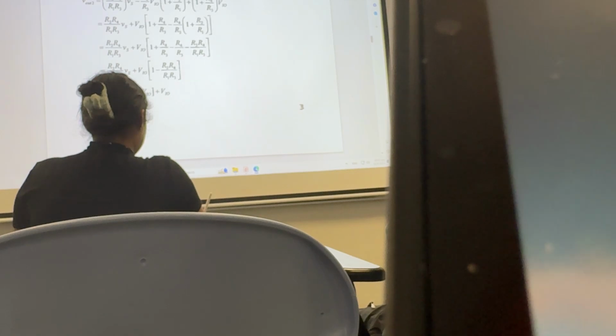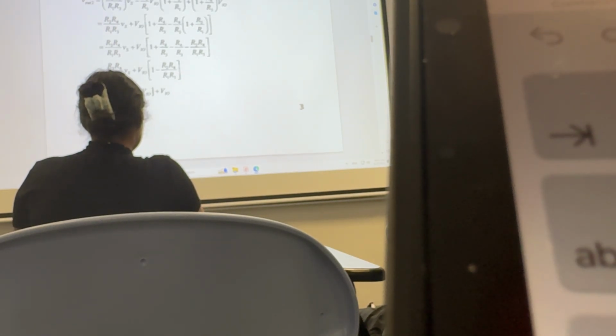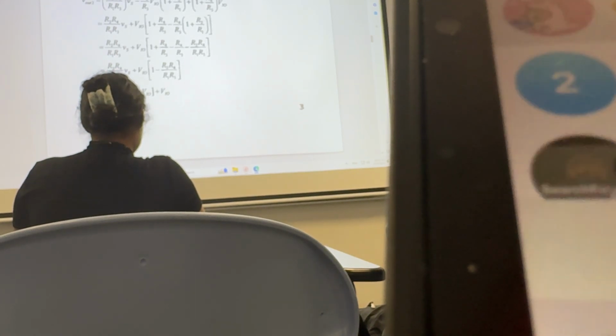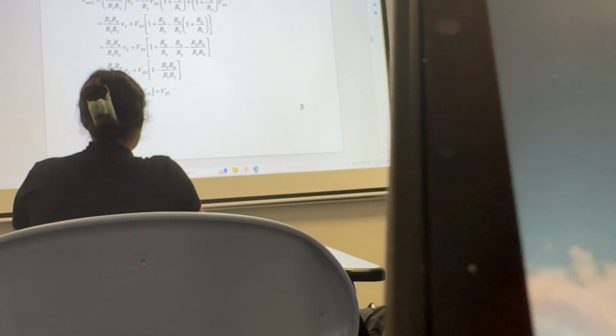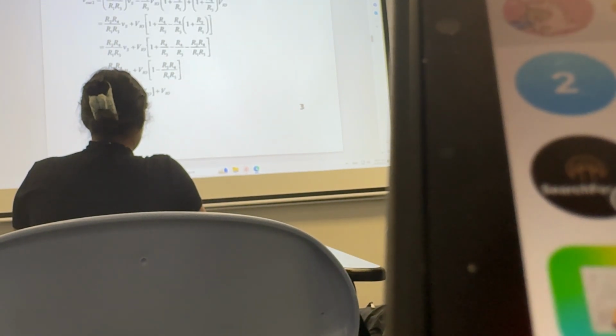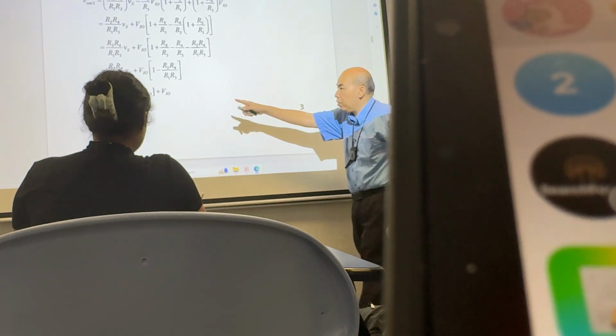So you have to be very careful. Now if you look at the 2 millivolt offset, what do you think about the output? You look at the picture, and for a bipolar supply, your offset should be here. If you don't have offset, it's 0, and you can swing. But unfortunately, you have VIO positive or negative 2 millivolt.